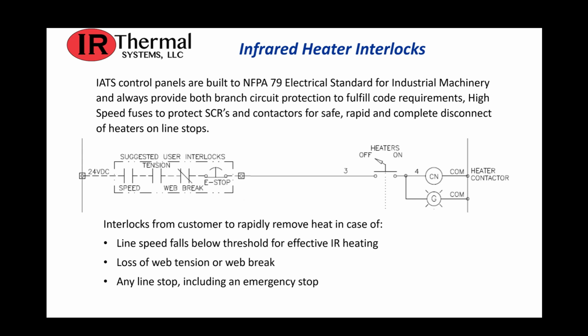So interlocks from the customer to rapidly remove heat are done in case of, number one, the line speed falls below the threshold for effective IR heating; the loss of web tension or web break occurs when you need to stop that heating; or any line stop in general, including an emergency stop. As soon as that's done, you've got to shut off those heaters as soon as possible.